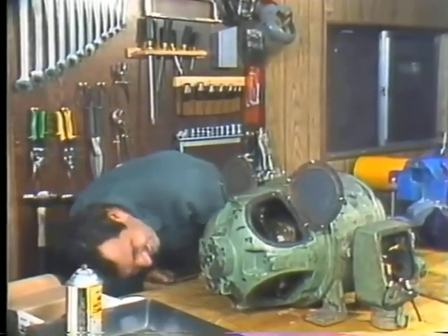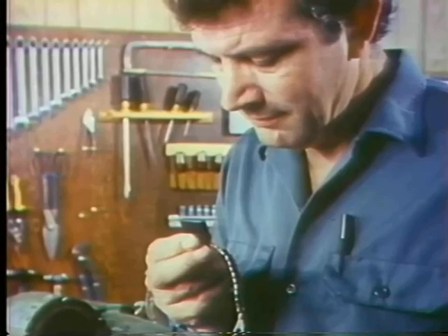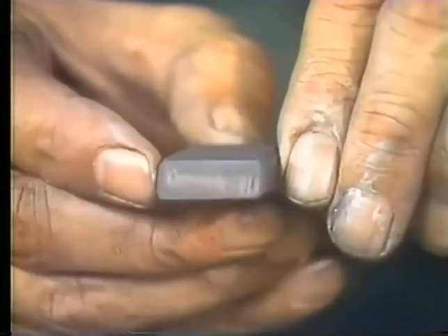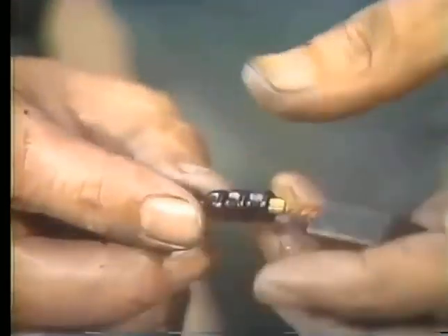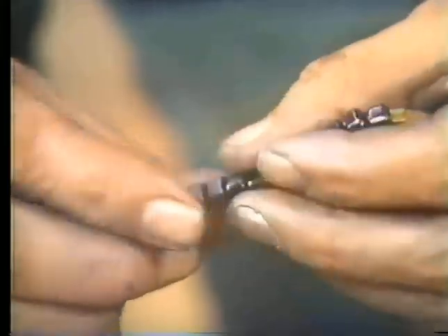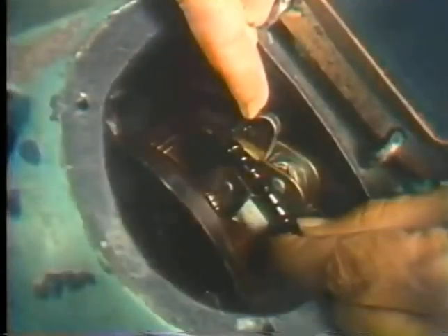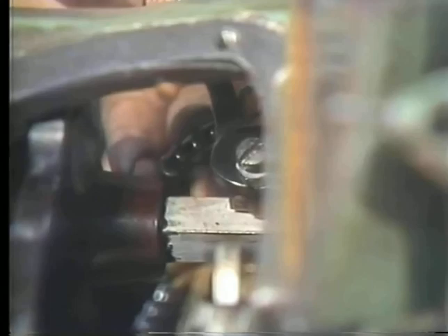All right, now let's look at our brushes. Remember what we said about the condition of the brushes? Make sure they're not too short and free of chips and cracks. Their contact surface should be shiny and smooth. The pigtail shouldn't be frayed. They should be flexible and securely fastened to the carbon. Place the brush in the holder. Set the tensioning device. Use the scale to give you proper brush pressure. Then connect the pigtail to the rigging.